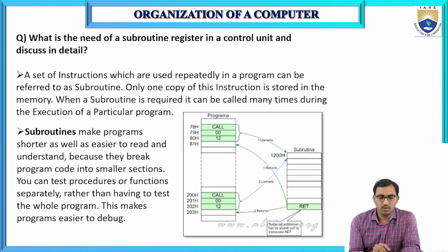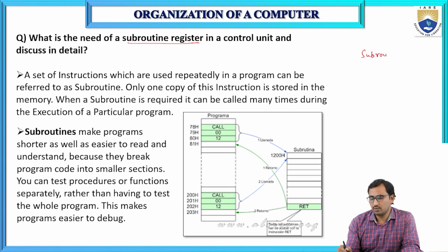So next one is: what is the need of subroutine register in a control unit, discuss in detail. So the subroutine register, we are especially using to store the return address. This is used especially when we are calling subroutines.